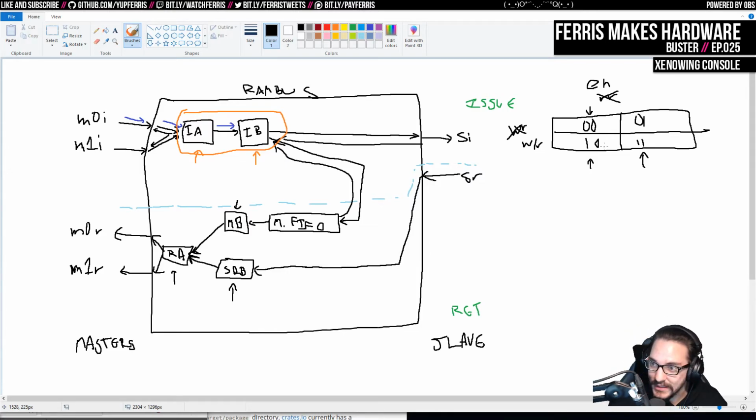And the other reason I did that is because when I had write request and read request as separate signals, I found that I was writing a lot of logic where I would just OR those together to determine if the master was trying to interact with the bus in the first place. So this kind of solves both problems: one, we've masked out invalid states, but also all that logic that I kept making to check if the bus was being interacted with is now natural, that's part of the bus signals already. So I'm pretty happy with that small aside there.